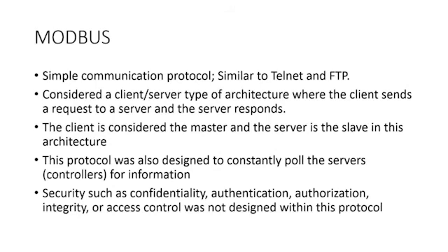Now, you might have something called Modbus with our SCADA systems. This is a simple communications protocol, kind of like Telnet and FTP, which should tell you what? Because we've already talked about Telnet and FTP, and we said they're what type of protocols. If you said unsecured, that's right. Because remember, we were using Telnet or FTP, and we had Wireshark or something like that, a protocol analyzer, wire sniffer, network sniffer hooked up there. We'd see those credentials going across in plain text, the username and password, not secure.